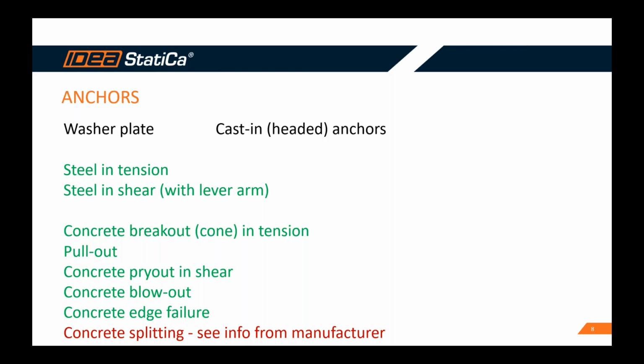About the concrete splitting, this is partially connected to the manufacturers of the anchors. Because we are using general anchors, this check has to be consulted with the manufacturer.